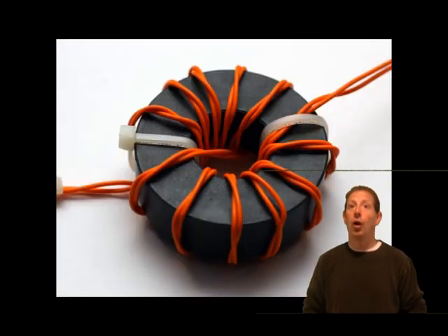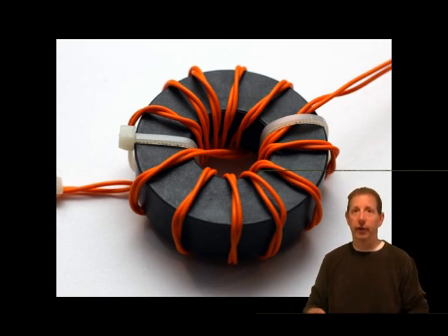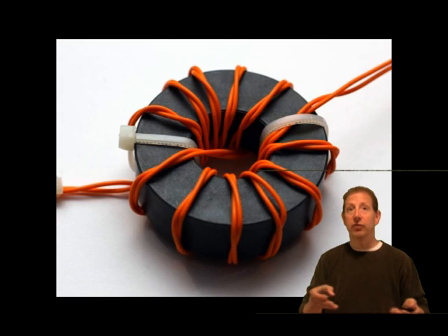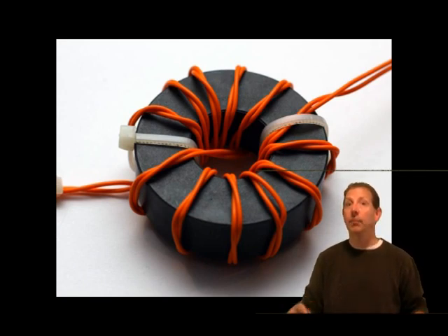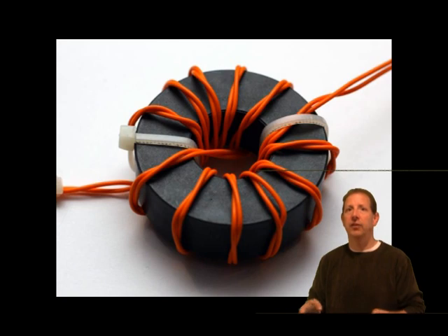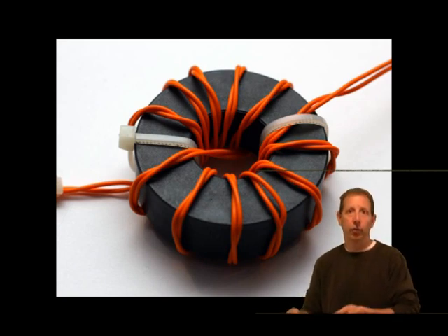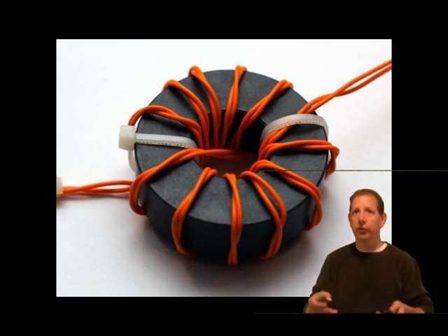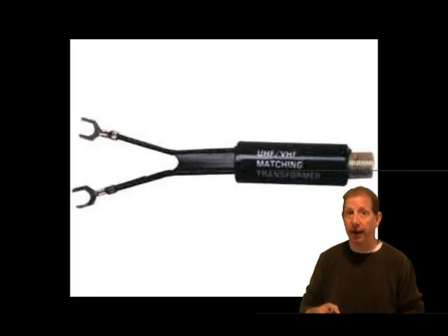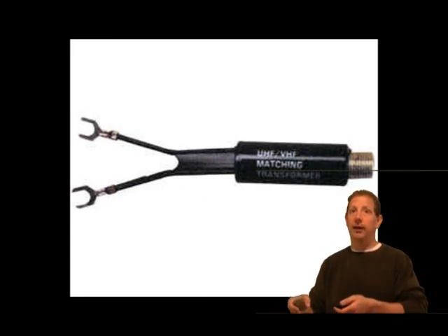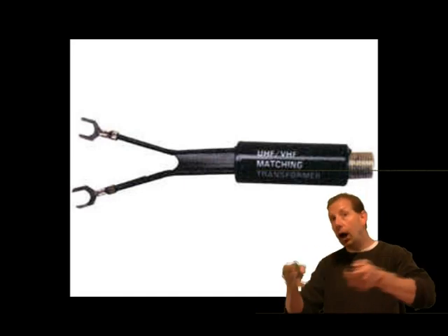And for those who are just reading through and aren't sure, a balun is an electrical device that converts between a balanced signal, two signals working against each other where ground is irrelevant, and an unbalanced signal, a single signal working against the ground or a pseudoground. A balun can take many forms and may include devices that also transform impedances, but need not do so. Transformer baluns can also be used to connect lines of differing impedance. The origin of the word balun is balanced plus unbalanced.